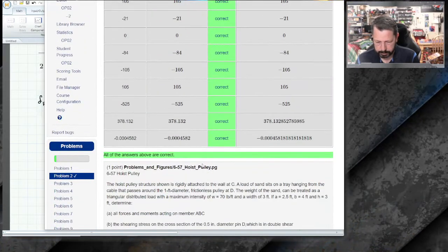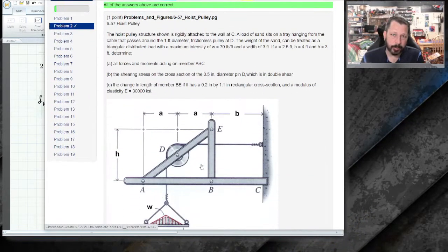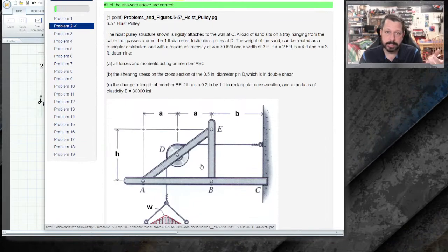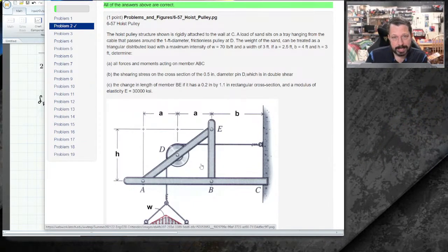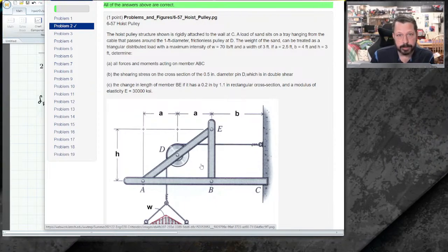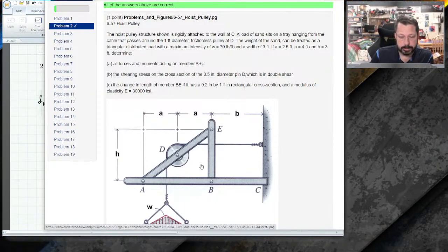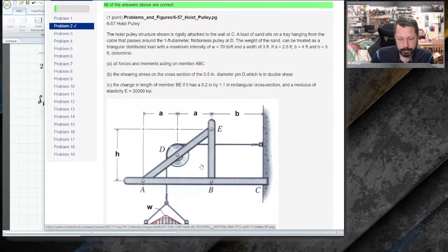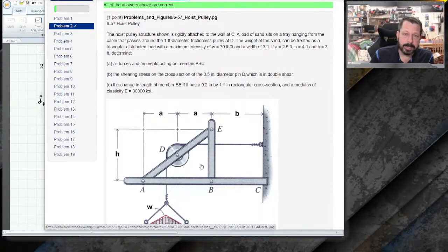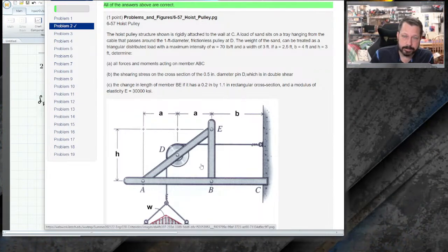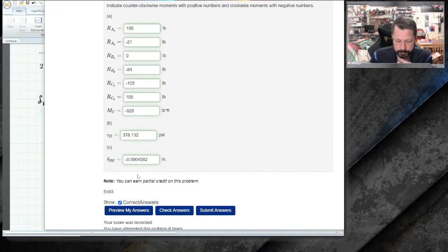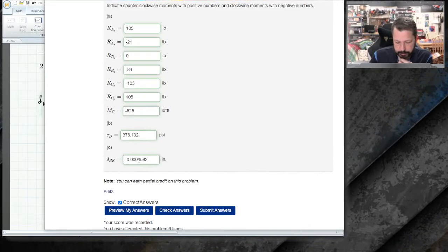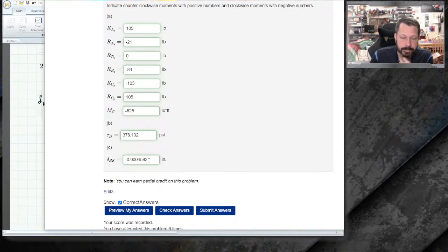It is correct. It's only 84 pounds in a 1 inch thick. This is a solid piece of 30 million PSI, the modulus of elasticity for steels. So this is a 1 inch thick piece of steel with 84 pounds on it. So it's not going to change length a lot with only 84 pounds. And sure enough, it's 4/10,000 or 5/10,000ths of an inch that it compressed.